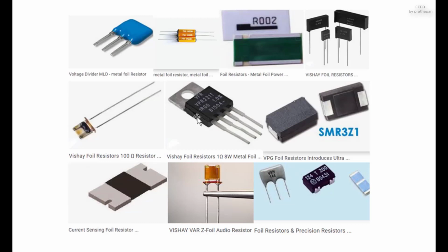Grid resistor. In heavy-duty industrial high-current applications, a grid resistor is a large convection-cooled lattice of stamped metal alloy strips connected in rows between 2 electrodes. Such industrial-grade resistors can be as large as a refrigerator. Some designs can handle over 500 amperes of current, with a range of resistances extending lower than 0.04 ohms. They are used in applications such as dynamic braking and load banking for locomotives and trams, neutral grounding for industrial AC distribution, control loads for cranes and heavy equipment, load testing of generators and harmonic filtering for electric substations.